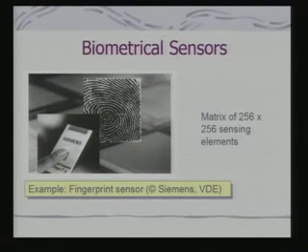That means if we are taking frames at the rate of say 25 hertz, and an image size of say 256 cross 256, then there is a definite timing window at which we have to obtain data for each pixel per frame. So our analog to digital conversion has to take place at that rate. And subsequently, I need to process this data for any kind of operations.